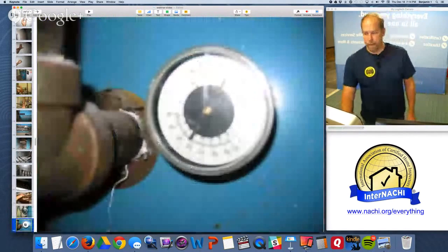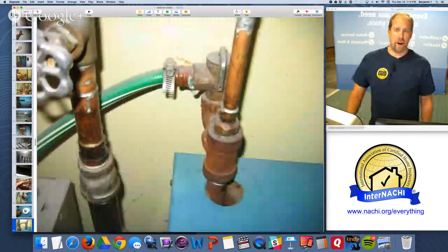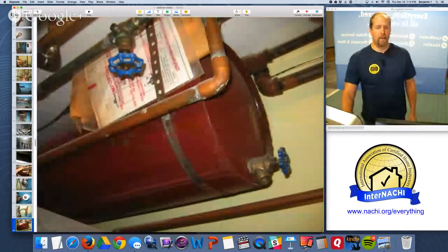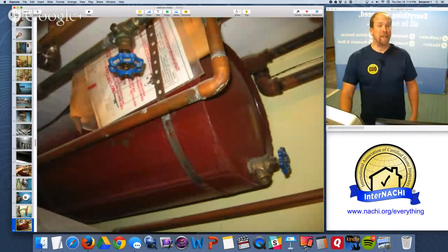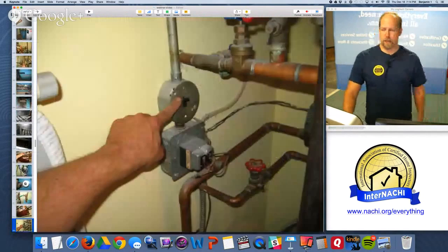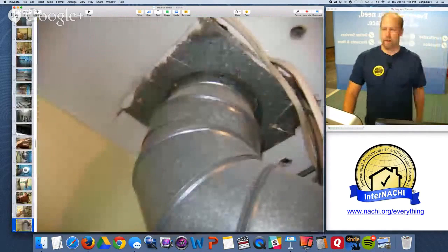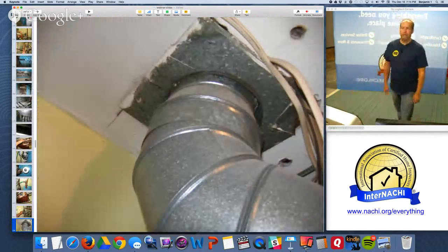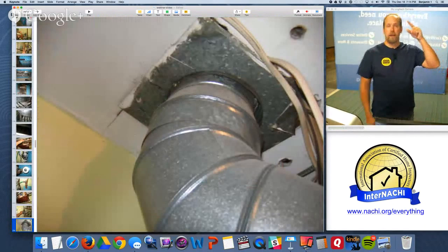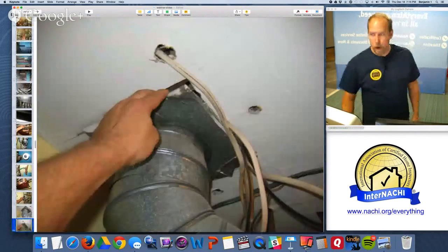That's a pump. Pressure, water temperature gauges, TPR valve, safety devices. There's an expansion tank. When water heats up, it needs to expand. This helps that expansion. A main shutoff switch to turn off the electric, a service switch. And then the flue pipe and a connection to the chimney. Remember the chimney, the rusted one? Dissimilar metals, galvanized rust. This is the bottom of it.